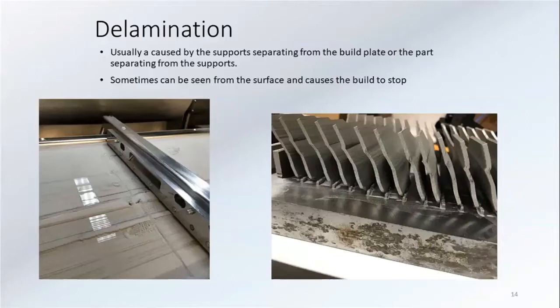And then as they moved up, you can see that they warped side to side a little bit, as the recoater is spreading, it can't smoothly spread that next layer, and so it's accounting for the differences as it goes up.